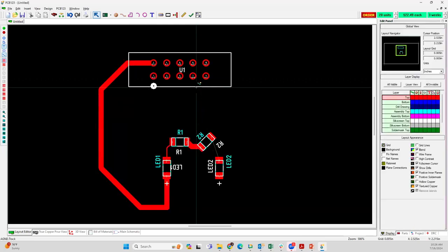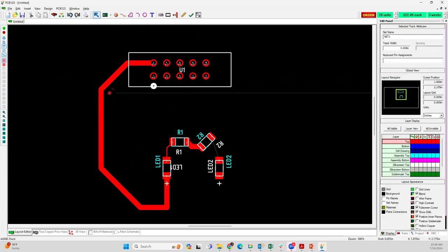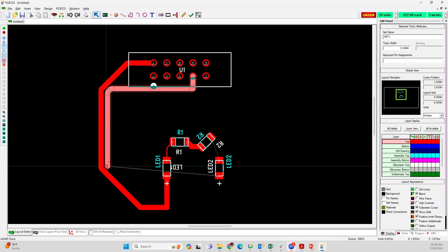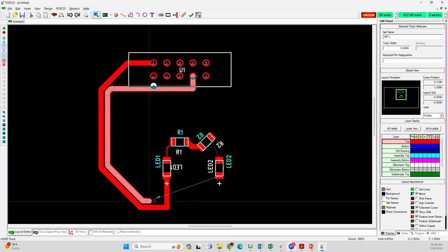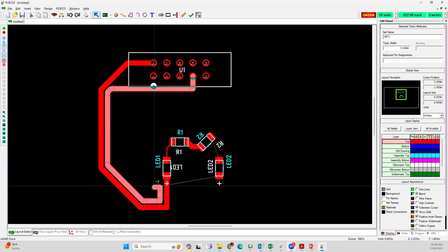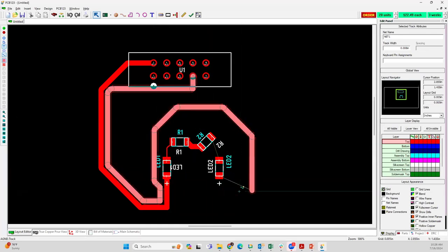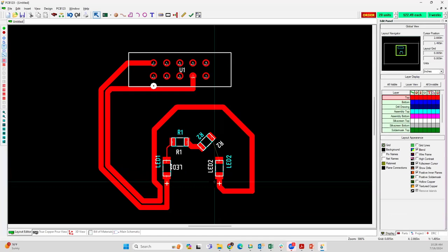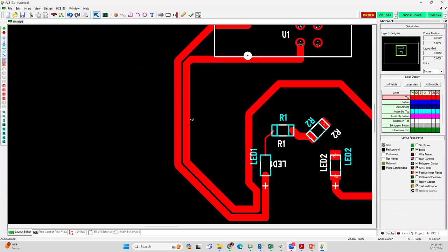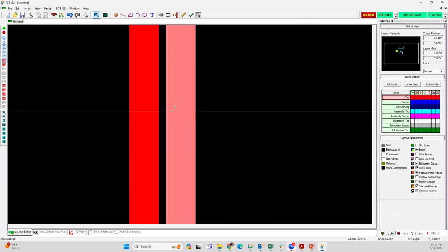and then I want to route this wire. You see it pops an error if you get too close. So you just put it right up next to the wire here, and you have an outline that you can follow to space your wires nicely. And you'd never do this. This is nothing you'd ever route like this. But you can. If you're doing differential pairs, high-speed wires, you can route together like that, and the spacing remains pretty constant.